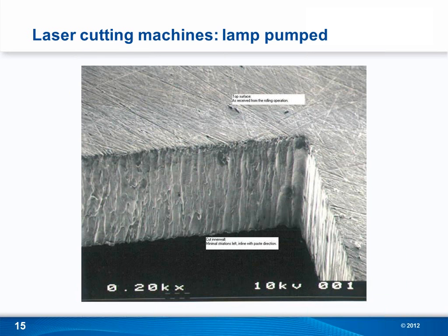When you look at a cross-section of the aperture walls in the stencil, you can see here in this picture there are still some striations due to the flow of the liquid metal that was blown away by the airflow or oxygen flow. The laser is actually pulsing, so little high energy pulses are used to nibble away the metal layer.